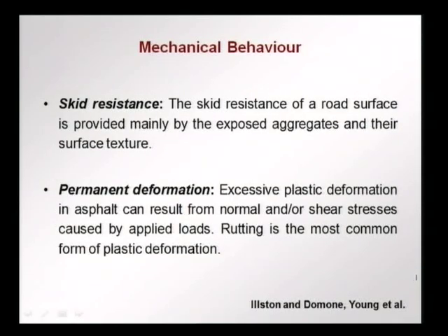Another very important aspect of a road surface is the skid resistance. Skid resistance influences the distance of braking and also the ability to ride on a road surface when the surface can be wet. And this skid resistance is provided in the asphalt concrete by exposed aggregates, the roughness provided by the aggregates and their surface texture.